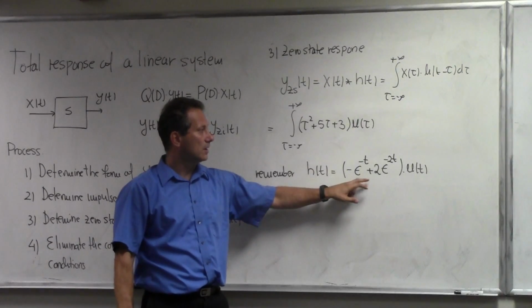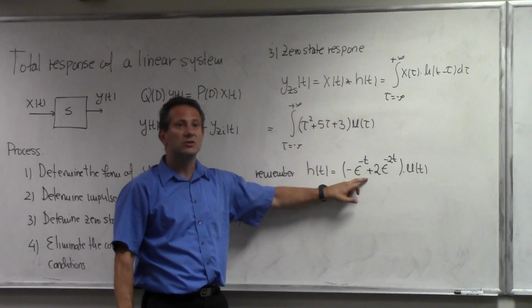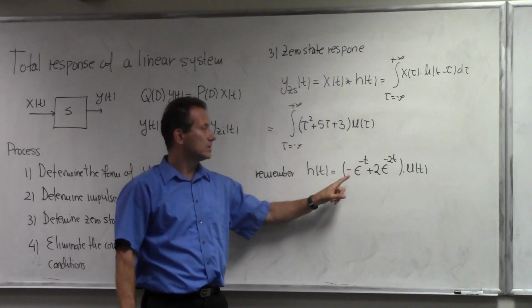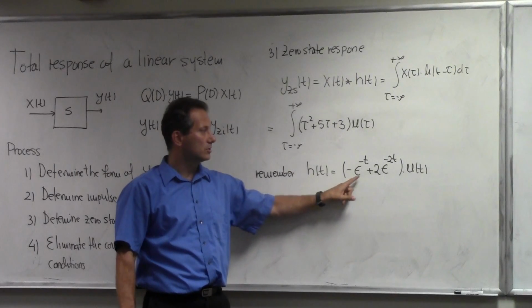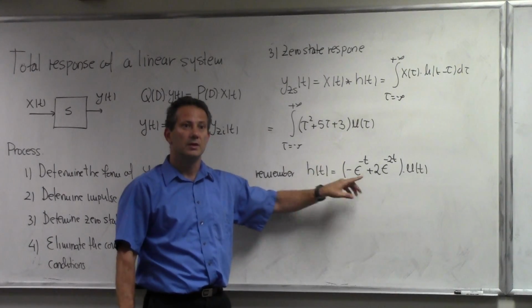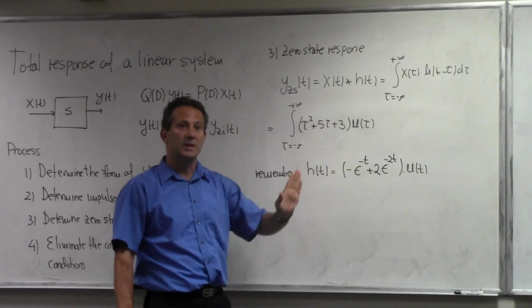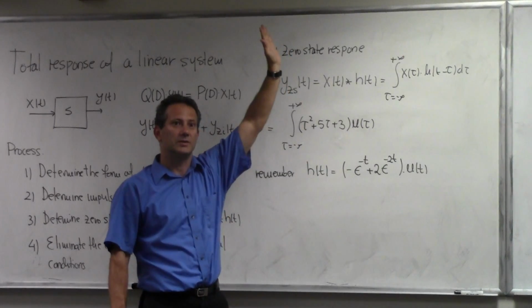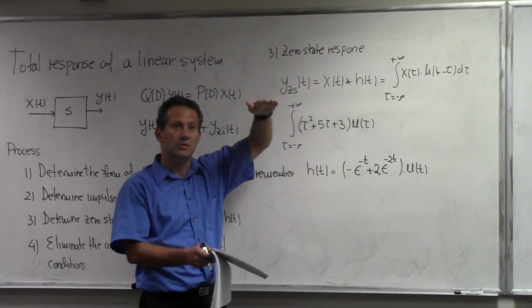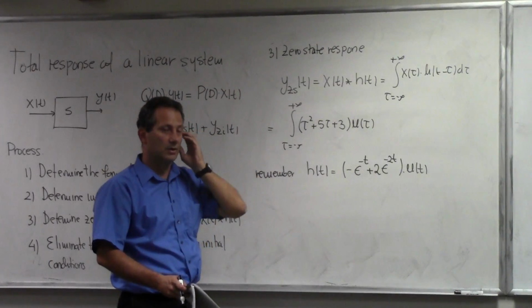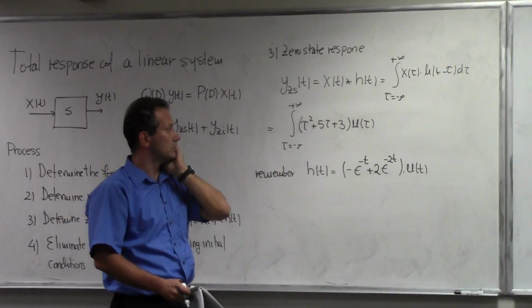Now you can see this has a discontinuity at 0. When you hit it with an impulse, what comes at the output at t equal to 0 has a value 1. So the response of the system was 0 before the impulse came in, but then it jumped from 0 to 1 as a result of the impulse. It has a discontinuity. It just didn't go to infinity because b0 is equal to 0.